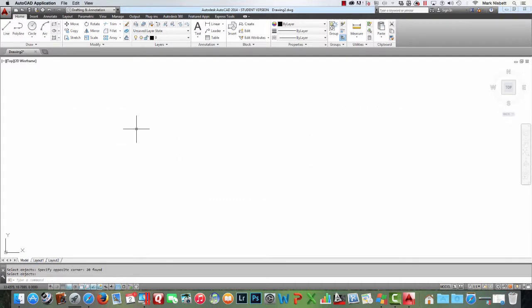So getting back to polylines again, what if we want to create like a big giant arrow head? When I use polyline, I'm going to come in here and click once, and I'm going to draw her up like this. But before I click the second time, notice we have arc, and then we have half width, length, undo, and width. Width and half width work basically in concert with each other. Width is the total width of the actual polyline, how thick it is, and half width is just that,